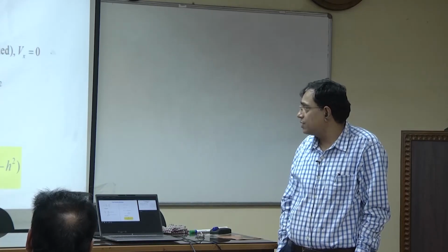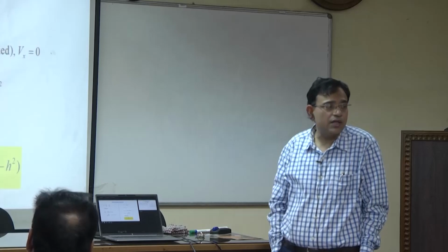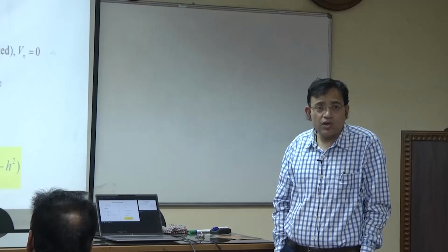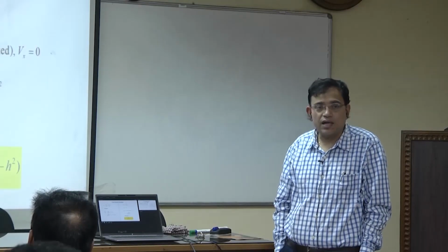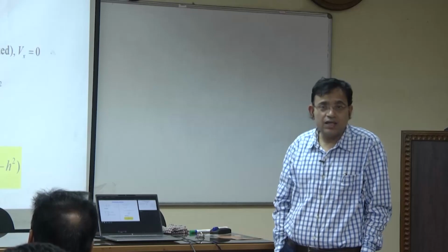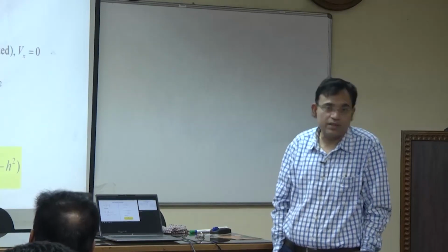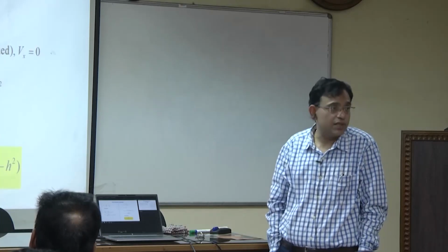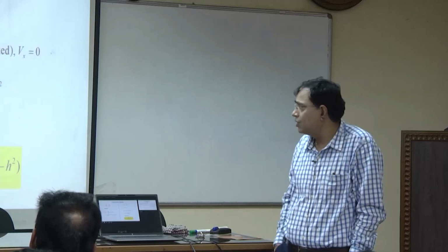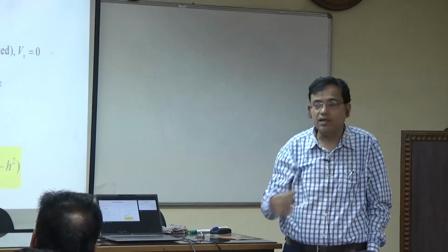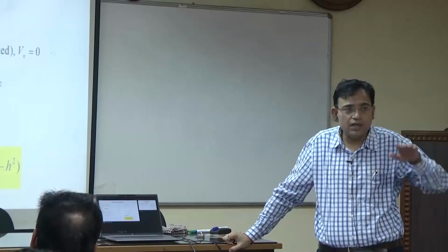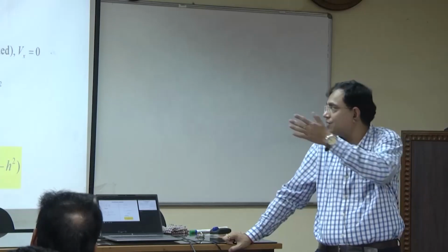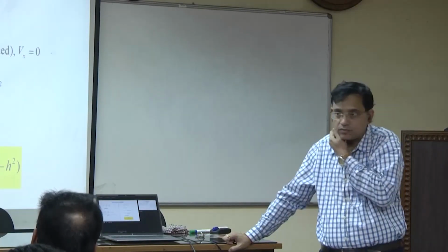One of the interesting things to note is that the constants of integration are not real constants, they are functions of both x and t. Why? Because the only difference between this and the classical channel flow is that classical channel height is fixed, and here the fluid domain height itself is a function of x and t, and that is why the so called constants of integration are functions of x and time. This we formally call partial integration. That means you are not really integrating it like an ordinary derivative, you integrate it partially where all other parameters other than y are like constants.